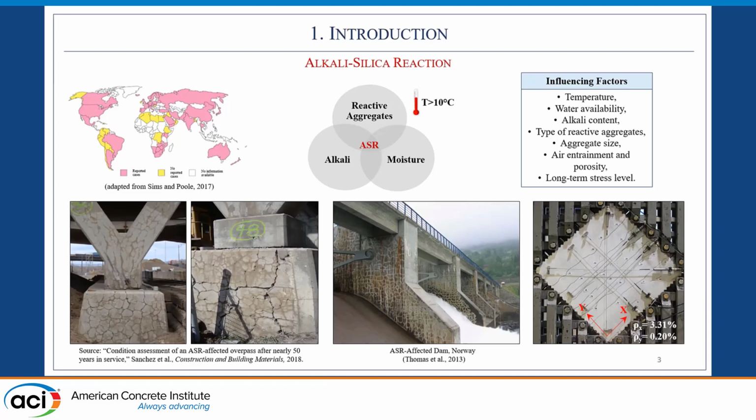ASR-affected structures may pose several issues, and one of them is increased seismic demand. Because of the ASR-induced expansion, we expect an ASR-affected structure to exhibit a higher seismic demand compared to a similar non-reactive structure. And this is because of the pre-stressing effect that ASR has on the reinforcement.